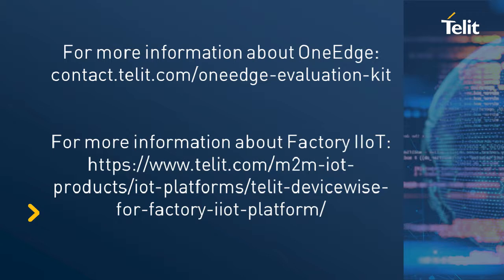Okay, question. Not clear how lightweight M2M is cheaper than MQTT for the same device. So if you just stack it side by side, same device, same use case. If I'm trying to do something with MQTT and I try to transmit that same data with lightweight M2M, you will generally find that the lightweight M2M transport uses between 50 and 70% less data.